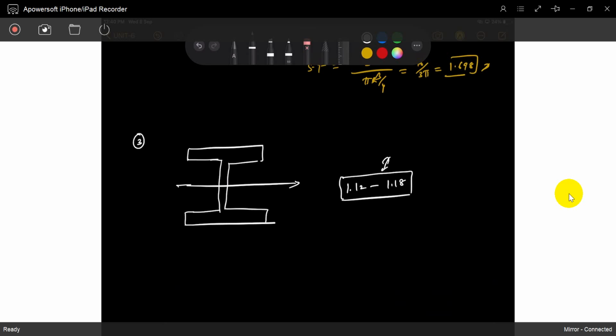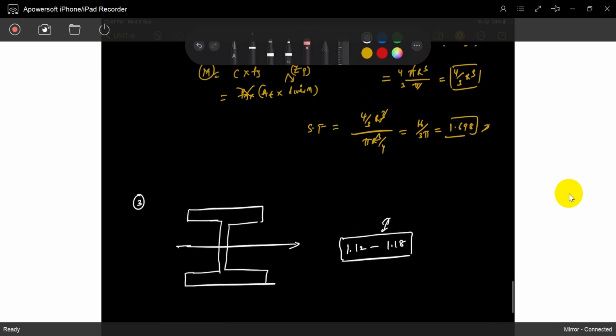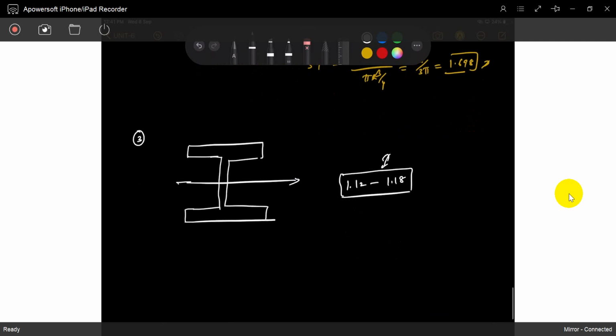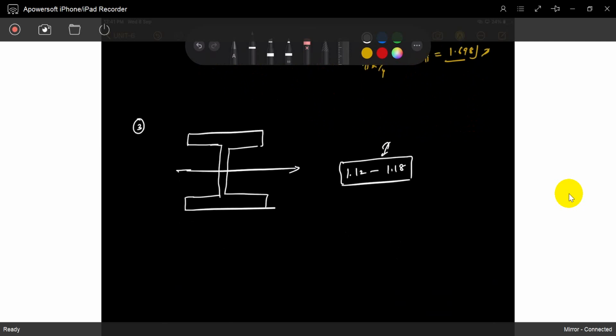So if you see this, you can conclude that only 10 to 20% strength remains after the yield point. So if you do the elastic analysis, it's okay. We don't waste so much energy. Only 20% is there. But if you see a circular section, 70% strength is there after the yield point, and that we won't utilize. Got the idea?